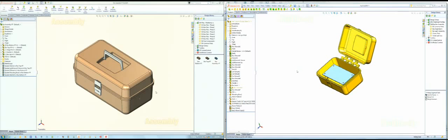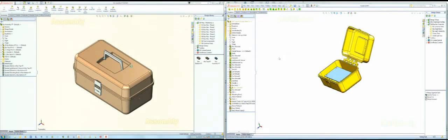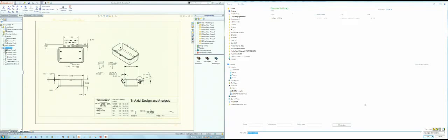Okay, next thing we want to look at is drawings. Relatively easy here. Most of you should be able to make an assembly drawing. Since I have an assembly and I've got individual parts, I can do that. Even with the in-context features in there, it still doesn't change anything. Because I've got all my materials in here, I can add a column to the bill of materials. I can also fully define each part as necessary on additional sheets or additional drawings. So nothing really big here.